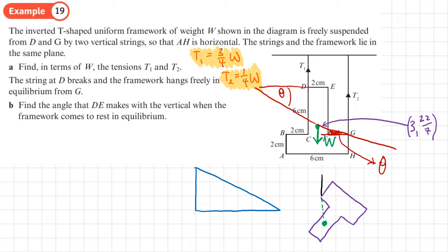So this is where the weight, center of mass is, W, sorry, it's at the top part of that triangle. So yeah, this is the point where W would be. This is the point G here at this end. Okay, and here's the vertical where W is. So what do we know? So the distance from G to that center of mass, we know this side length is 3 because that's dead center here. Then we want to work out this length here.